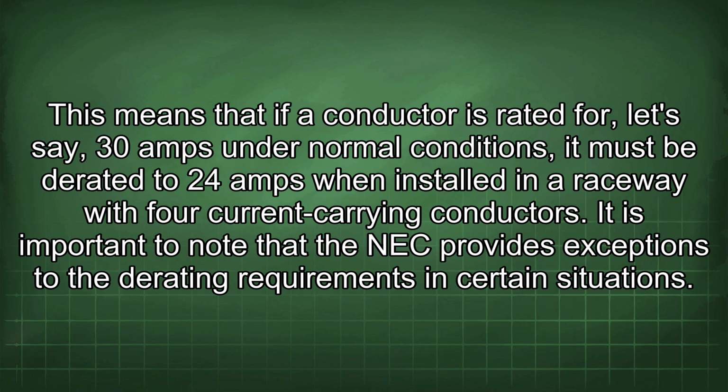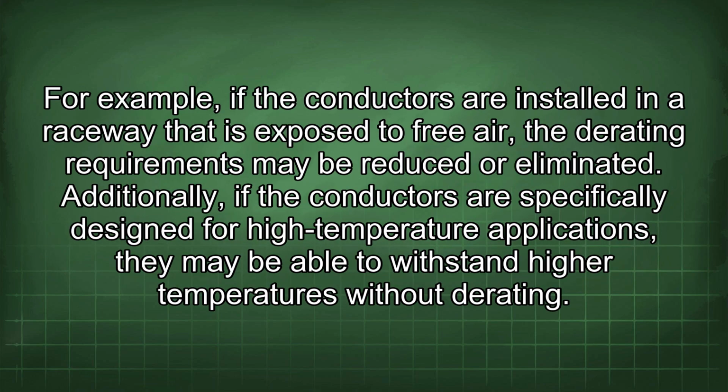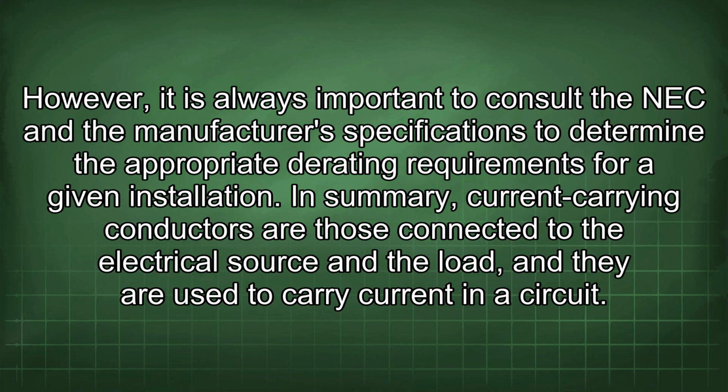It is important to note that the NEC provides exceptions to the derating requirements in certain situations. For example, if the conductors are installed in a raceway that is exposed to free air, the derating requirements may be reduced or eliminated. Additionally, if the conductors are specifically designed for high-temperature applications, they may be able to withstand higher temperatures without derating. However, it is always important to consult the NEC and the manufacturer's specifications to determine the appropriate derating requirements for a given installation.